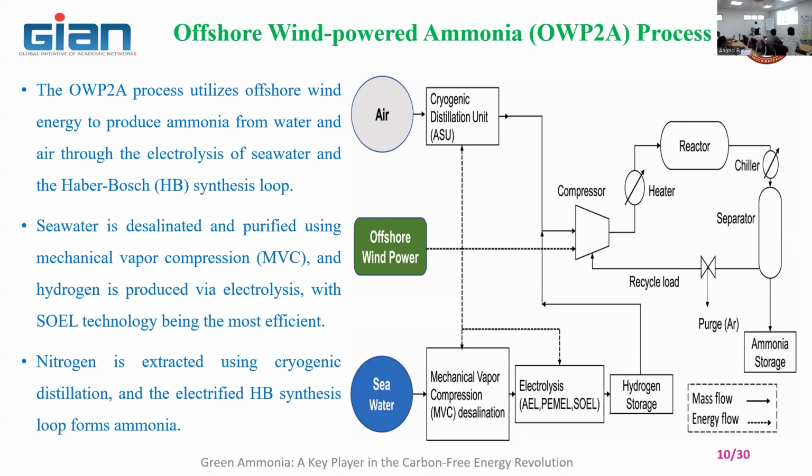Then you take it to a reactor, something like a Haber-Bosch reactor. The hydrogen and nitrogen go in, and we maintain a pressure of 100 to 300 bar by using a compressor. To raise the pressure from the input pressure to the required reactor pressure, we take work from the surroundings, from the wind energy conversion system. Now you are raising the pressure to about 200 to 300 bar, but we need temperature also to produce